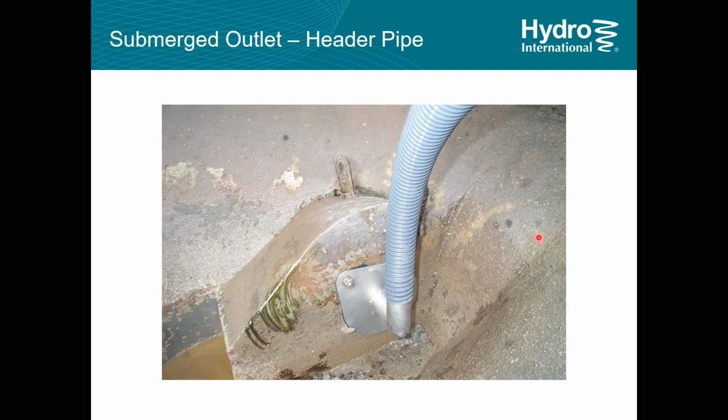Now, the other thing you see here is there's a gate on the back of this valve. Most of our valves come with these gates, which are usually hooked up to a pull cord. They're a solid gate, and you could then open those gates manually if you required to increase the flow, or for inspection, or to allow cameras or jet systems to pass through them. So the valves can be maintained, cleared, and inspected very easily.